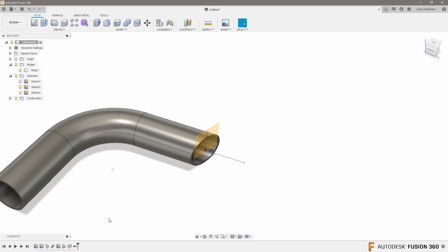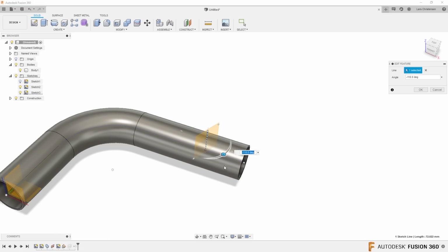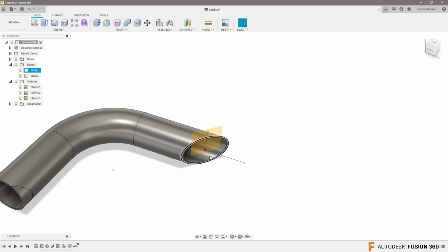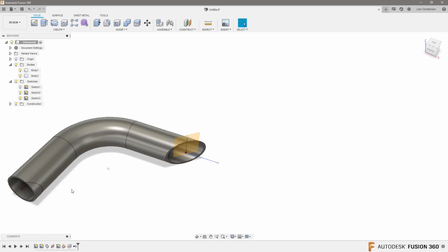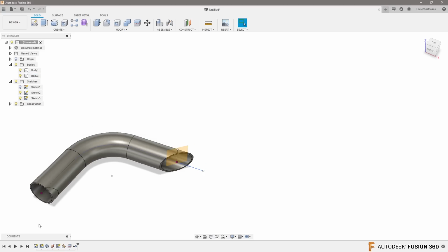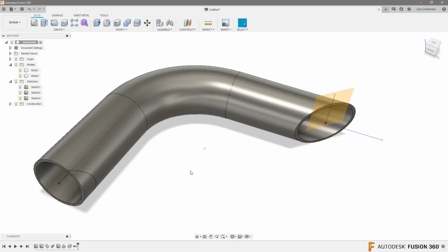as an end result. And of course, if I go in and I change that degree I had in here on this plane, let's do it 130, that will reflect that too. But oh, now it's actually cutting through. See how that plane? See how we suddenly got a sliver down here? This is a good one. This is a typical example where you're modeling something up and you're like, why did I suddenly get this sliver down here? That's not fair.